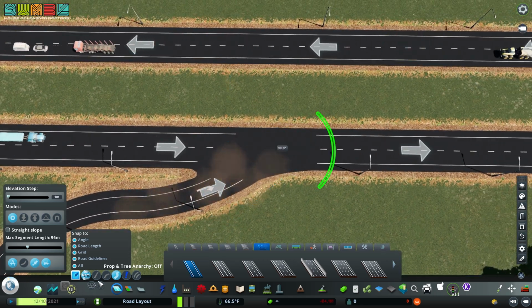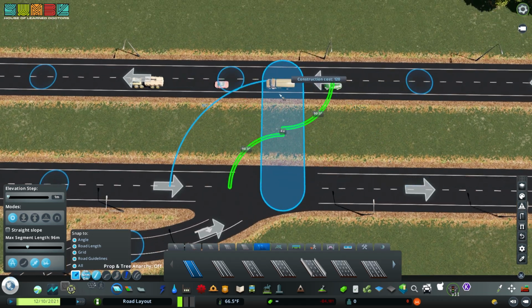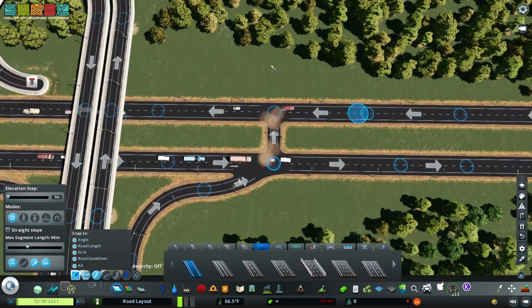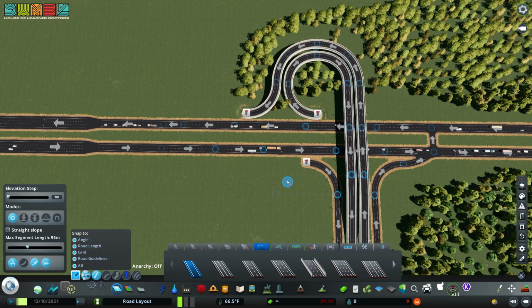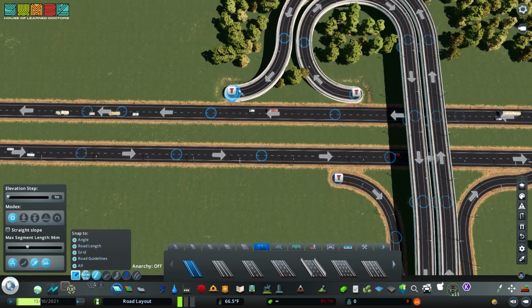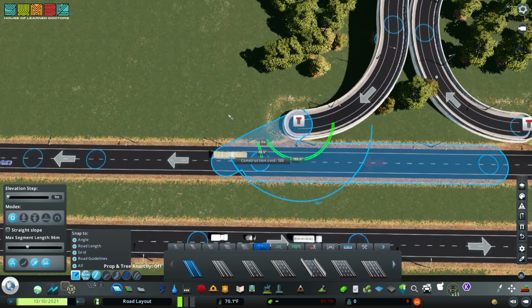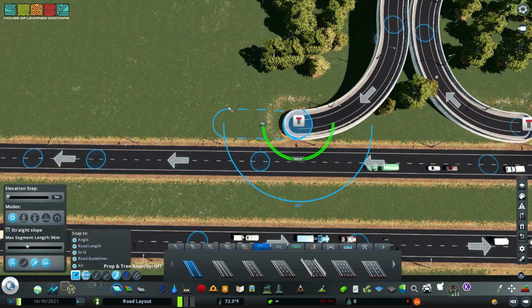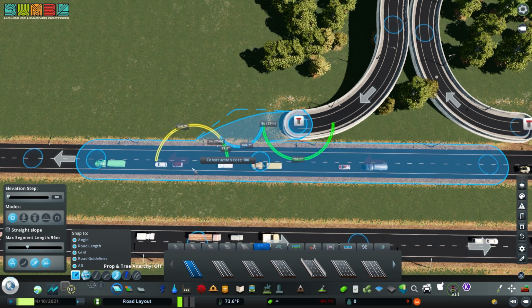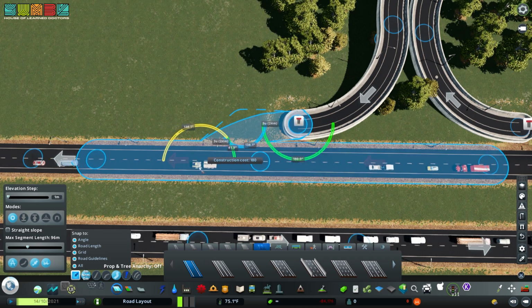Beautiful. And I want that to be the same on the other side, so we're going to, once again, force a node at 90 degrees. That gives us our node there. Same thing over here, because this side is actually our furthest point. I want to see where 24 meters lives, using the freeform road tool. 24 by 24, rather. 24 meters.